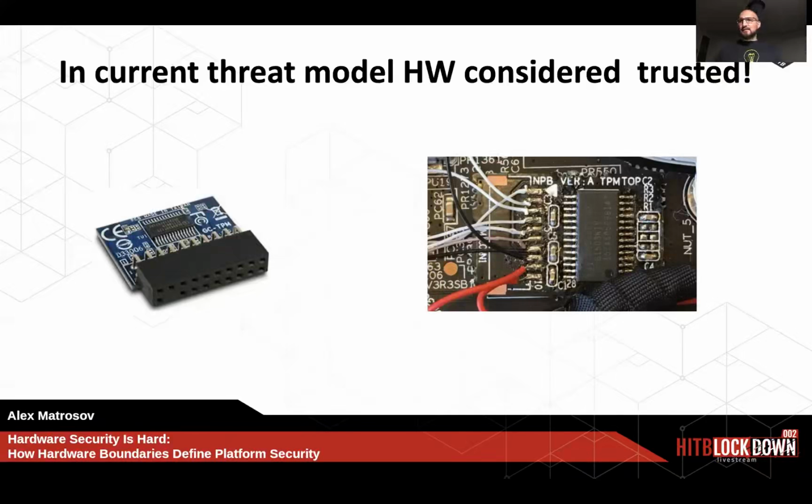And there was brilliant research from Jeremy Boone about a TPM interposer, and Trammell Hudson actually did something different, a different way, but also interposing TPM signals by soldering direct wires onto the chip. And you can see this in the picture. A lot of server boards actually have a separate TPM, which is just connected on a slot, and you can see it on the left side of the slide, which is also hard to consider a trusted root of trust, right?